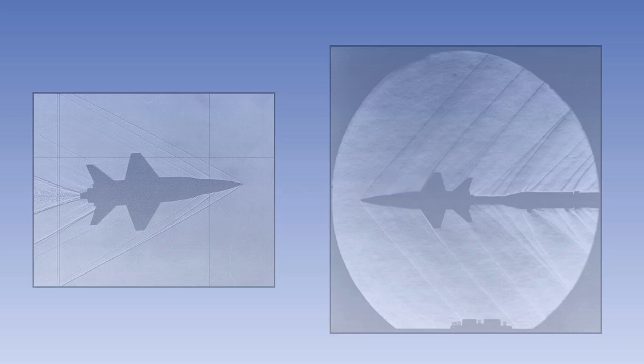As the aeroplane's speed approaches Mach 1, the compressibility and approaching shock wave can have very detrimental effects on the aeroplane's performance if the aeroplane is not designed to mitigate such effects. As a result, most commercial aeroplanes in service today have a limit on the maximum Mach number they are allowed to fly at. This maximum operating Mach number is called MMO.